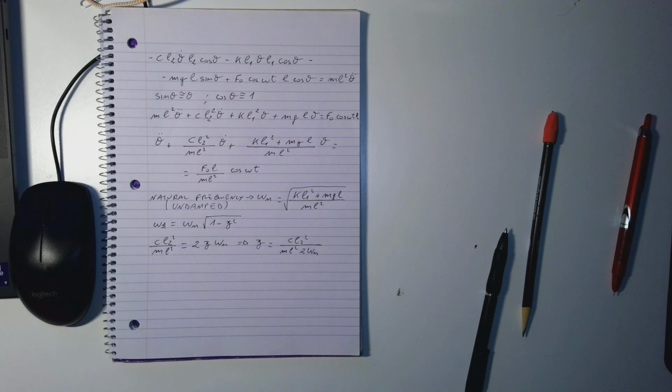Make sense? So remember, when we talk about the natural frequency equal to the square root of k over m, again, that is valid only when we have a simple harmonic oscillator. So mass and spring. Okay? When we start to play a little bit with the geometry, or when we have a rotational body instead of a translational body, we have to be careful, because what we have to do is look at the standard form of the equation of motion.